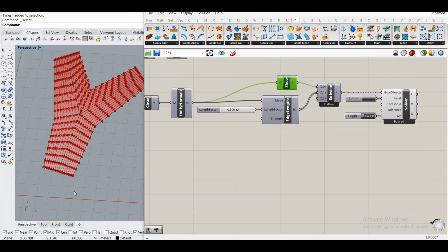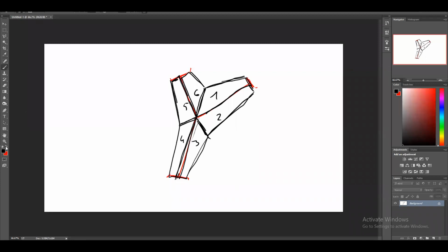In this case, previously, what we've done is we've just said, give me the outer perimeter of the mesh, and lock all of the points around the outside boundary. In this case, we don't want that. We just want the points which are here, here, and here. Only these points we want to be locked.